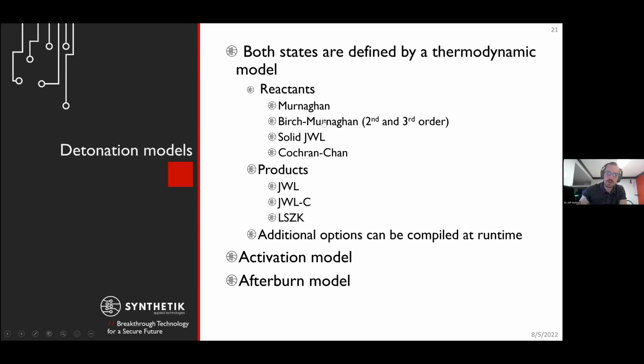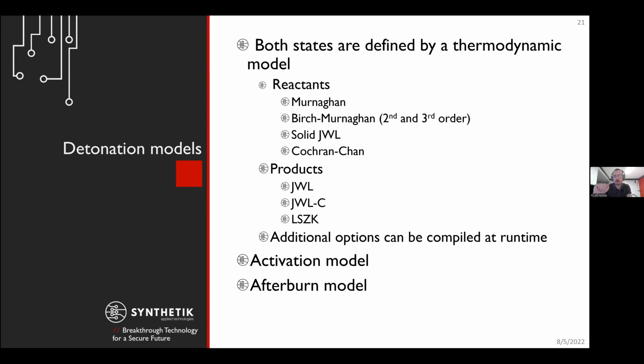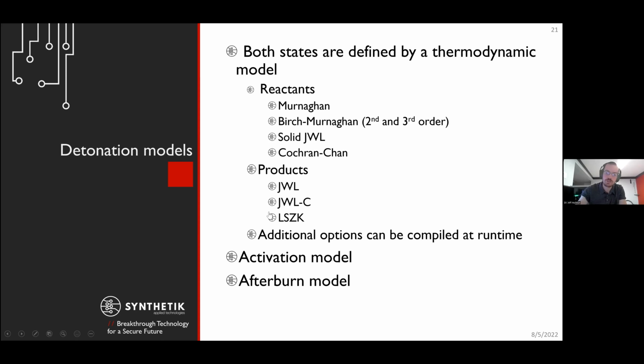So both of the products and reactants are defined by a unique thermodynamic model. So like all OpenFOAM simulations, you have your transport, you have your energy, and you have your equation of state. So you need all three of those for both the reactants and products. So these are specifically the equations of state. There's nothing really different about the viscosity or the transport models or the energy models.